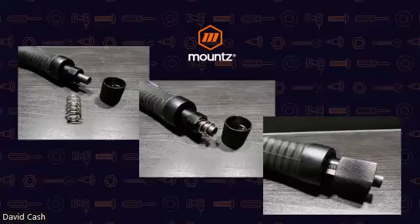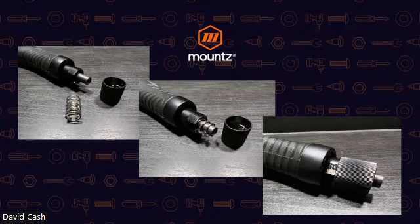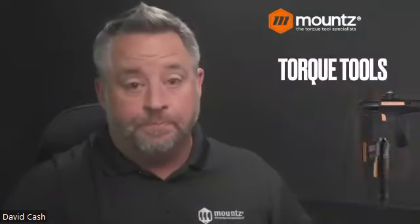They're not providing us with what the torque output is for that screwdriver, but we can correlate those reference marks if we use a torque analyzer to validate where that is for that specific tool. And then we can use that type of reference. But again, the spring is what is being compressed to give us the actual torque output. And that's how most electric torque screwdrivers function.